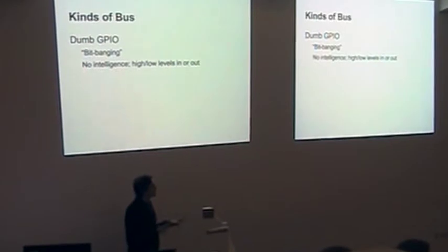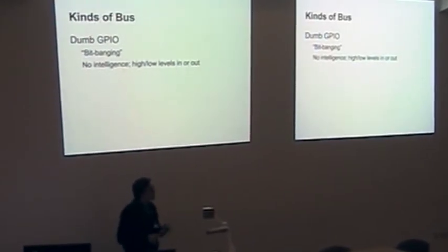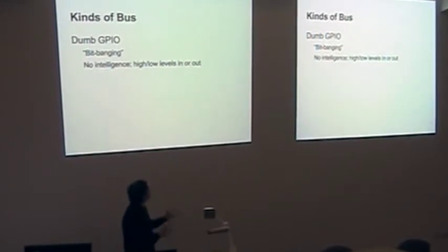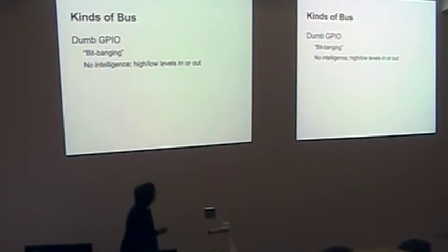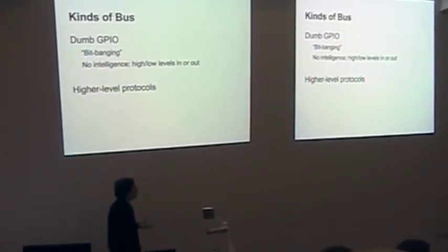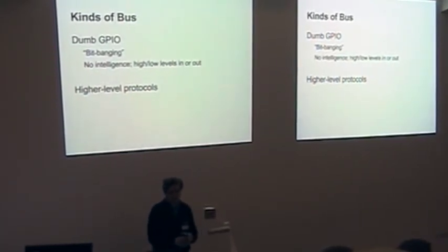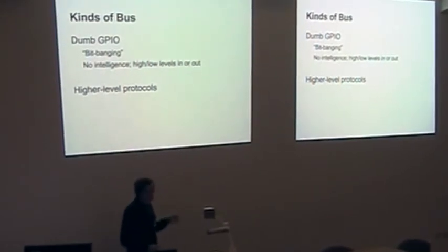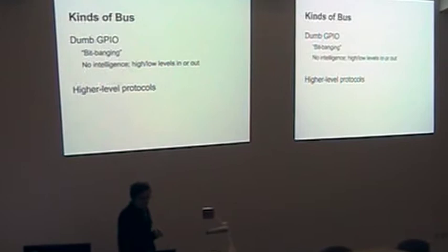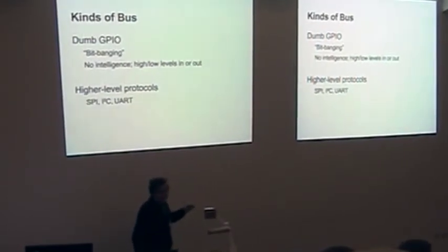It's very low level, very manual, very, very slow to do anything interesting, but generally pretty universal because you're in full control of the pins. You can live your life, you can talk to crazy weird hardware devices that are very weird and silly. But it's not very useful because almost all of the chips that you'll buy, sort of radio modules or LCD controllers or whatever, will be talking some sort of slightly higher level electronic protocol. Primarily, there are the two main ones called SPI and I2C.